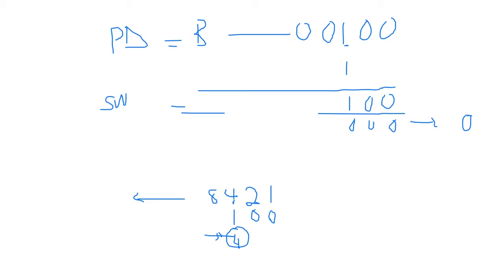Which is great, but not ideal. So basically we have the switch value being equal to 4 at this point. Even though we read from it, the value is 4, which is 1, 0, 0. But all we are interested in is whether the switch is a 1 or a 0. We don't want to deal with large numbers or anything. So what we can do at this stage, where we have switch being equal to 1, 0, 0, of course some byte up to bit 8, is shift it backwards.